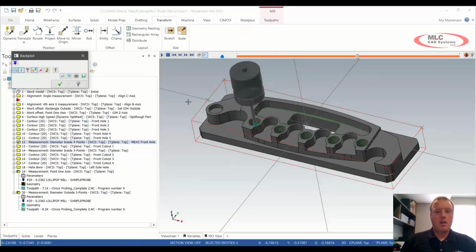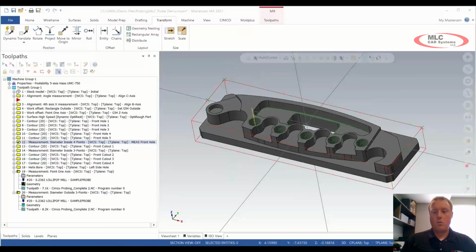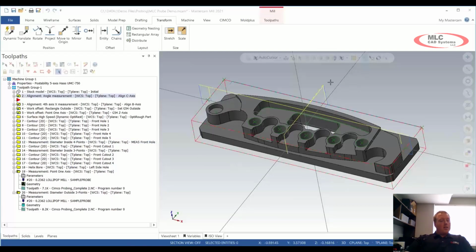Now with that, we are given a couple different options, whether I'm wanting to do that as a 3-point or a 4-point cycle, though it's kind of up to you when programming as far as telling it what we want to do. The difference between those is a 3-point is going to allow you to select the different vector angles of the part, where a 4-point is then going to keep that at 0, 90, 180, and 270.